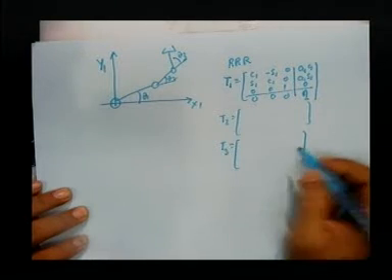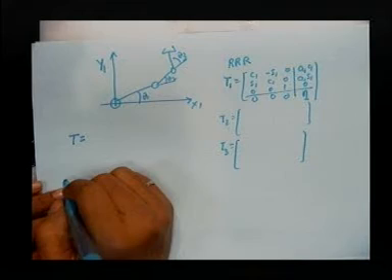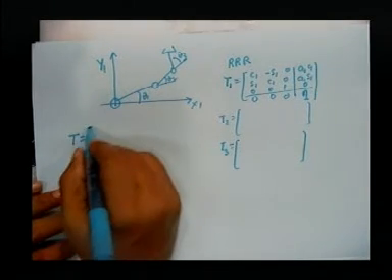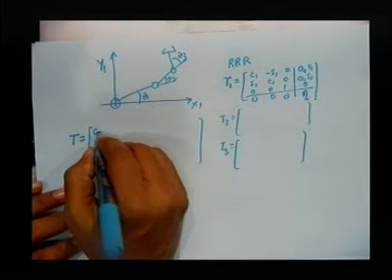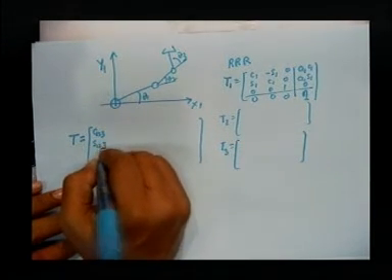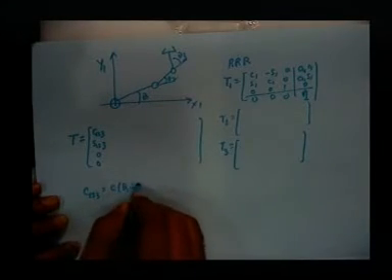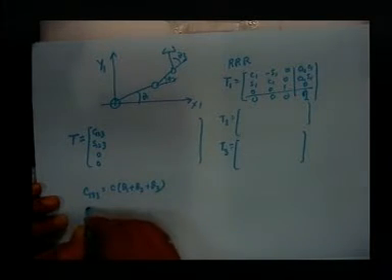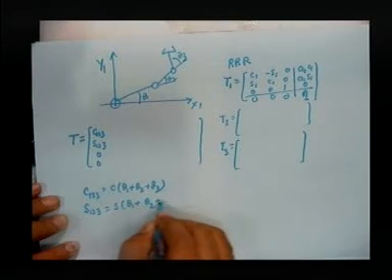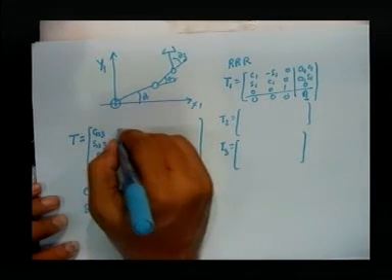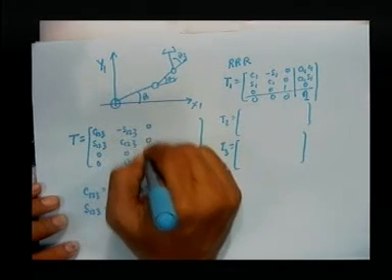Going by the analogy of the 2R, one can show that this one will be cos 123, sin 123, 0, 0. Cos 123 means cos of theta 1 plus theta 2 plus theta 3. Similarly, sin 123 means the sine of the same sum, so this will be sin 123, cos 123, 0, 0, 0, 0, 1, 0.